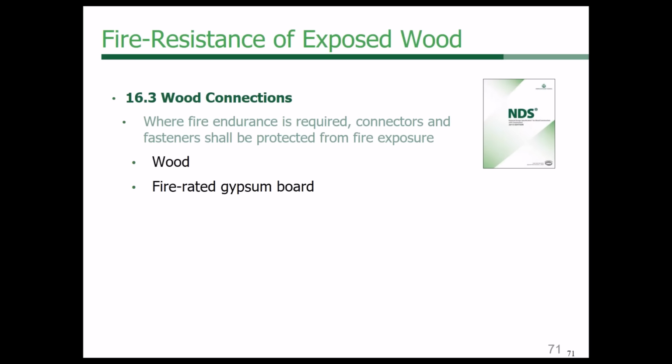Now, one thing to note, if you're calculating the fire resistance of an exposed wood member, we want to make sure that not only are we calculating the fire resistance of that wood member, but we have to look at it as a system. So the cross-laminated timber, wherever it spans to and whatever it's supporting, the connections of that cross-laminated timber to the wall or whatever need to have the same amount of fire resistance that was calculated for that cross-laminated timber.